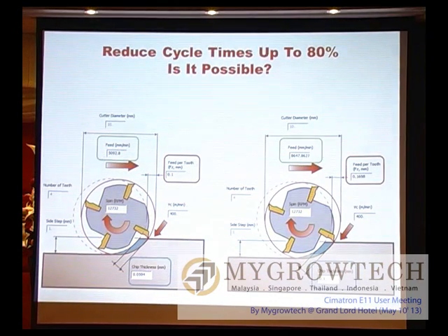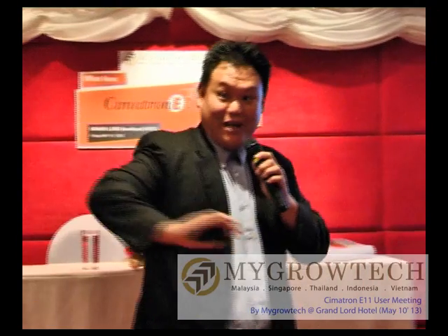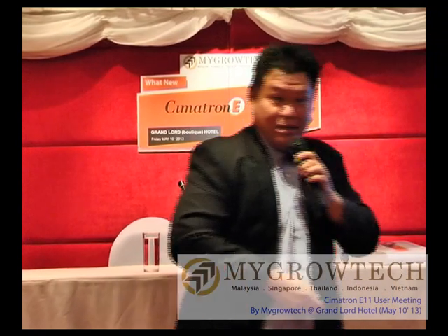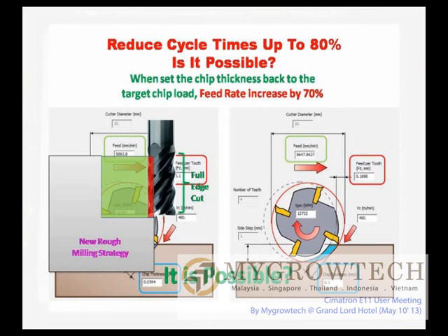So next picture. I increase this one to 0.1. You can see the current feed per tooth is 0.1698. Already increased. With this feed per tooth, I'm actually cutting at 8,600 feed rate. Of course, my cutting speed is 400, let's assume. The old one is only 5,000. So from this calculation, simple math, the feed rate of your cutting is increased by 70%.